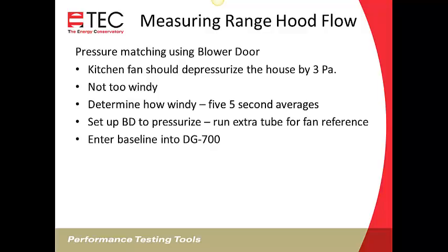Then we're going to have to cap the fan, and if you don't have one of those shower cap like fan caps, you'll need to cover that opening. Either go outside and cap the fan, come inside, enter your baseline reading, and then go back outside and uncap it, or you'll need to seal that blower door opening from the inside to get your baseline reading. It's important to get that baseline reading entered into your DG700 in order to get an accurate measurement.